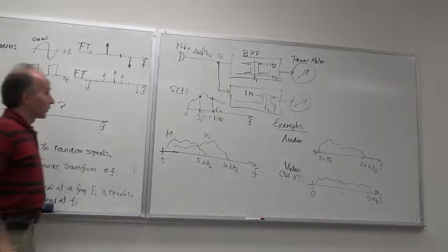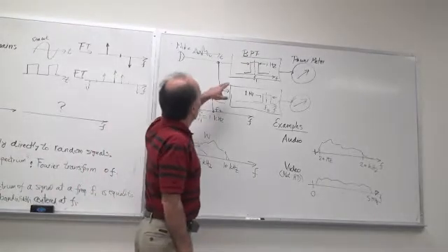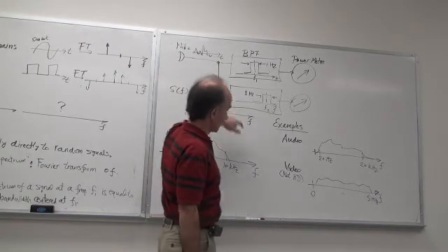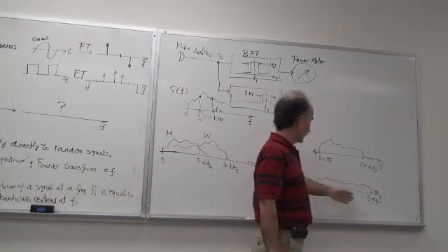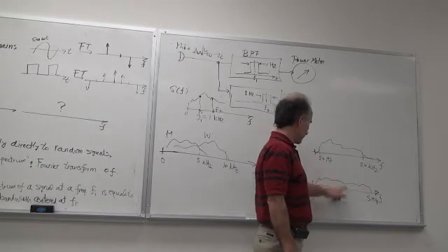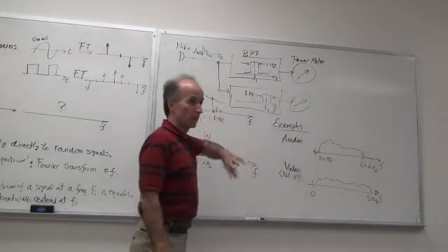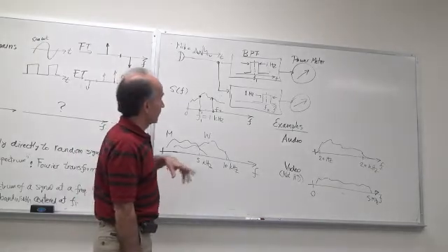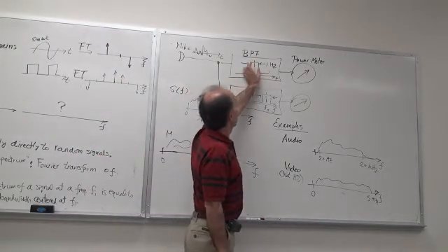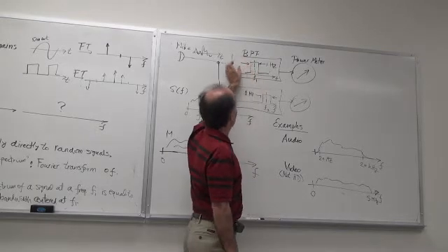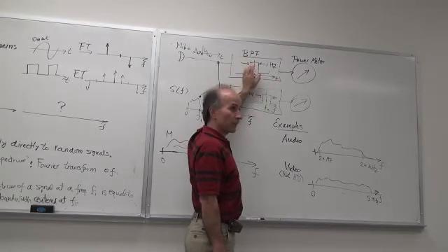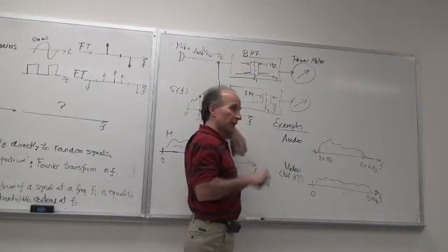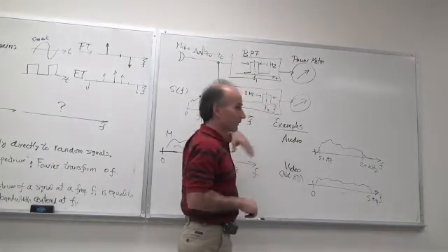All right. Now, a couple of notes. Number one, do we really need this many filters here? That seems rather complicated, right? So how do we do this exactly? If I want to measure from close to 0 to 5 megahertz, you need this many bandpass filters. So that would be impractical. That's not something we can do. So in reality, you can have maybe one filter, and this bandpass filter can be programmed. You can go up and down the frequency. Imagine there's some sort of capacitor somewhere, and you switch more capacitance or less capacitance, so you move the center frequency up and down. Or there are other techniques. So in reality, we don't use this many filters.